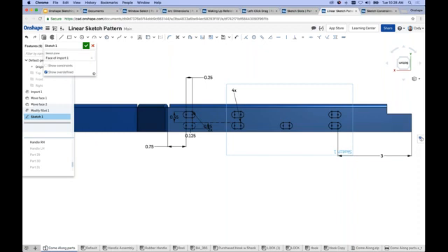Yeah. A linear pattern at feature level, you would hide an instance rather than delete. Again, we don't have a hide equivalent, so we do delete the geometry. When I window select an instance within the pattern, it deletes it. It can always be brought back again with an undo or something along those lines, but it is a true delete, not a hide. You could use two construction lines, and this is a reference to the question earlier.